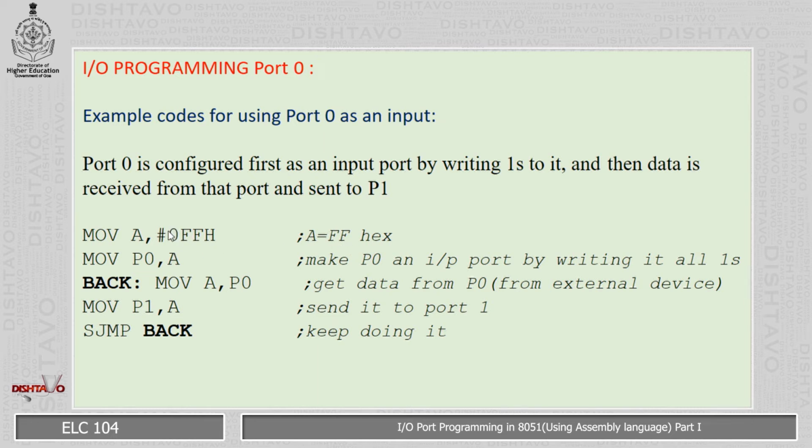Now please note that you have to put a numeric value whenever you have an alphabetical value. Your hex values go from 0 to F, so you have A, B, C, D, E, F. For the assembler to understand that you are giving some data, I have to put a 0 whenever you are giving a hex value. If the first part is an alphabet, then you will have to provide a 0 before it.